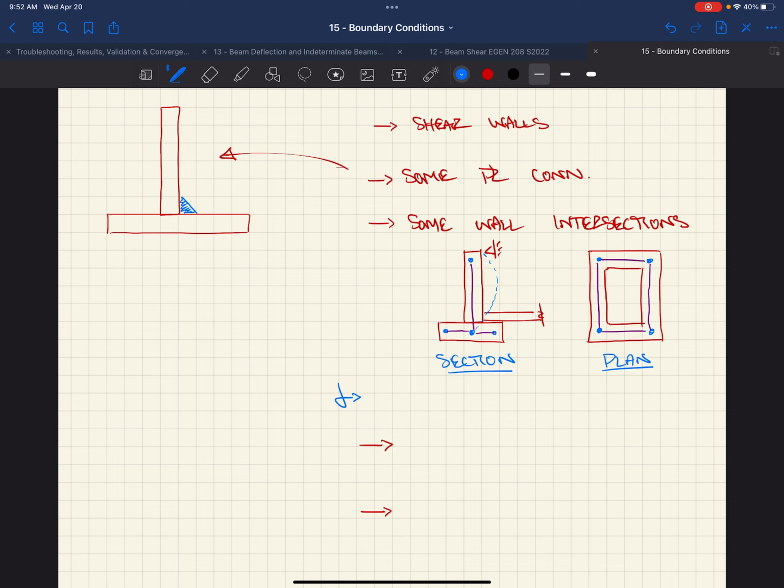And then you want a model description as well. I want a list, and if you were here at the beginning of class, Amanda had a great question about whether or not you need to describe why you changed that. And yes, you need to describe why you changed those things too. It doesn't need to be a paragraph, just say, this node was 2 feet off, I moved it to align with the model, or it doesn't match the layout that you gave us. It can be as simple as that, but I want to know why you got rid of it, why you moved it, why you changed the load on it, why you changed the releases. A lot of them could be: it doesn't match the layout, it doesn't match the behavior of the shear tab, it doesn't match this, it doesn't match that. Okay?